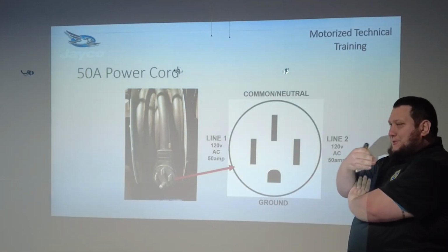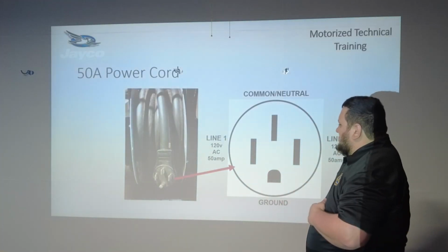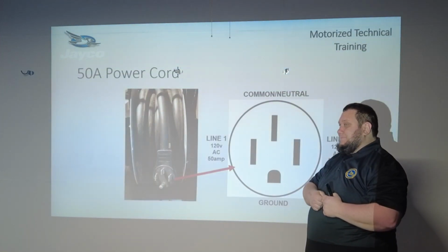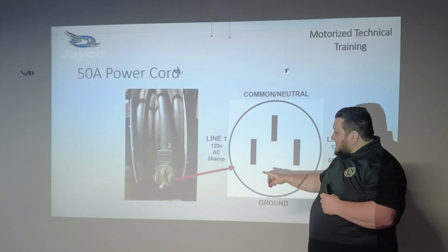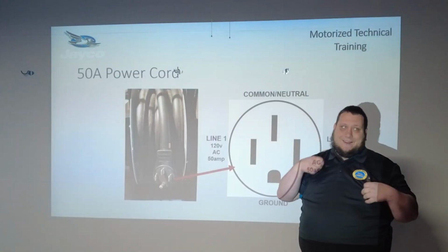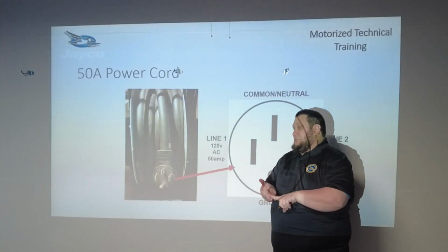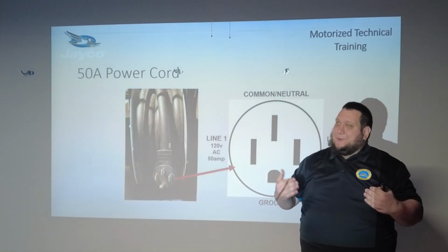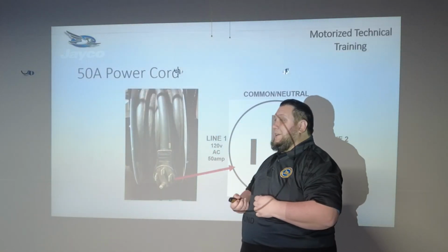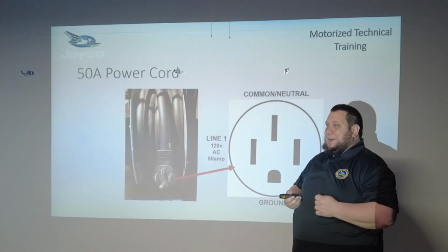Most often in any sort of electrical troubleshooting, any sort of electrical problem you're having, 50% of the time it's going to be a blown breaker or fuse. And most often those are going to be caused by a loose connection somewhere in the system rather than a rodent chewing on something, a staple through a wire, or even a customer doing anything wrong. A vast majority, I would say, of any electrical problems that a customer is going to experience in their RV are going to be loose connection. And that's the hazard of taking a house and driving it down the road.